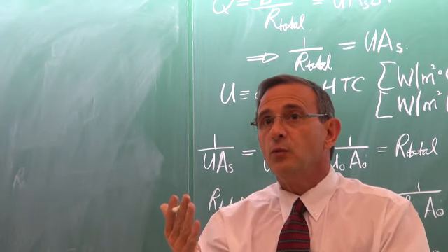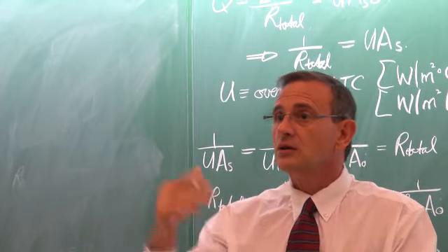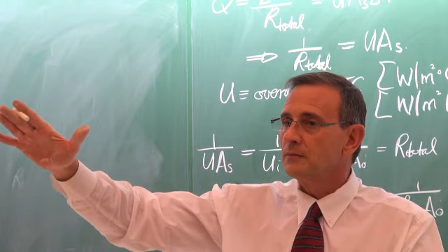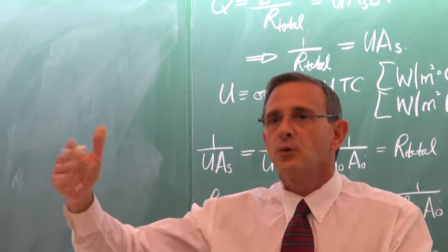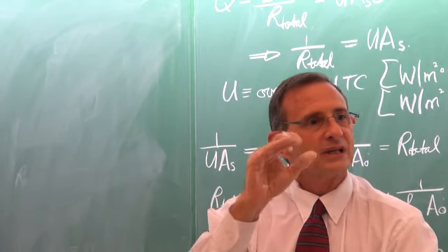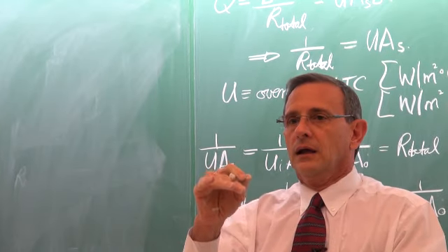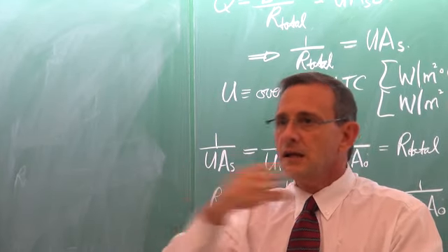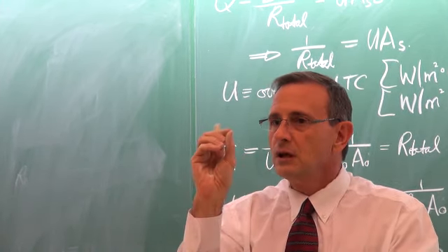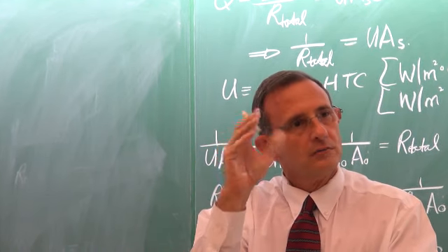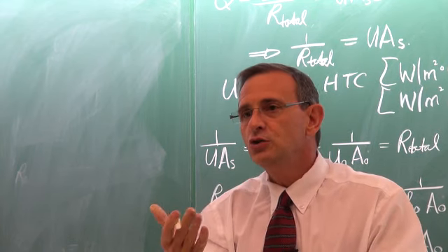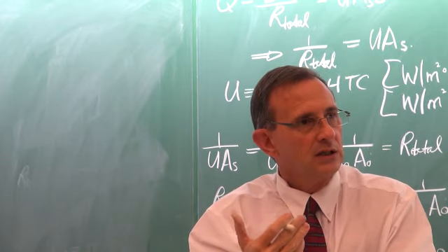Then, the other type of problem that we have is with finned heat exchangers. Typically on the outside of buildings, we've got condensers or evaporators with fins. Okay. And the wind blows, and what happens when the wind blows? You get a leaf that gets in between the fins, you start getting dust, and then it rains a little bit and everything stays there, and then there's a little bit more wind, etc. With time, and there's also pollution, there will be a buildup of scale or fouling on the outside of the heat transfer area. And we need to take that into consideration when we design heat exchangers.